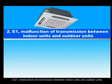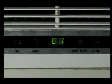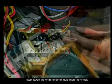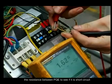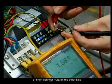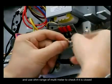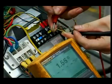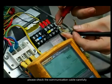2. E1, malfunction of transmission between indoor units and outdoor units. Repair instructions when E1 appears. Step 1. Use the OHM range of the multimeter to check the resistance between PQE to see if it is a short circuit, or short connect PQE on the other side, and use the OHM range of the multimeter to check if it is closed, to confirm if the communication cable is broken or not. If a short circuit or open circuit happened, please check the communication cable carefully.